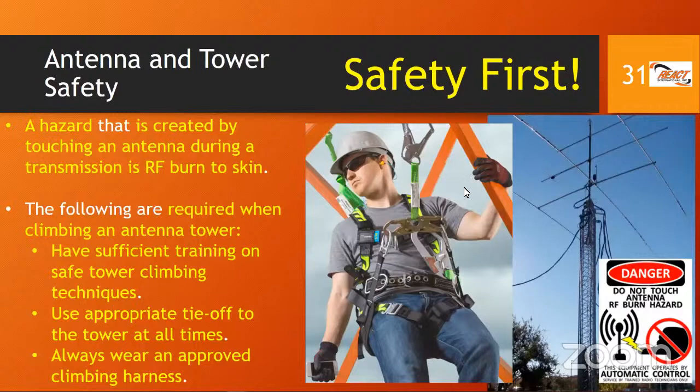Second point is, if you're climbing the tower, make sure you have tie-offs. So in case you were to slip or fall, you have tie-offs so you wouldn't fall too far. So you need to have tie-offs on the tower at all times. And also, you need to wear an approved safety harness. It must be inspected before use each time and make sure that it's good and it's approved. So this is a safety harness that this guy is using here. Nice, keeping him safe from falls and all of that.